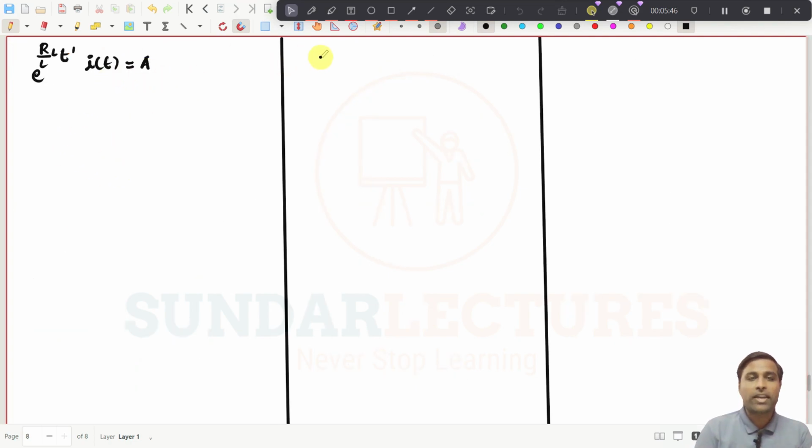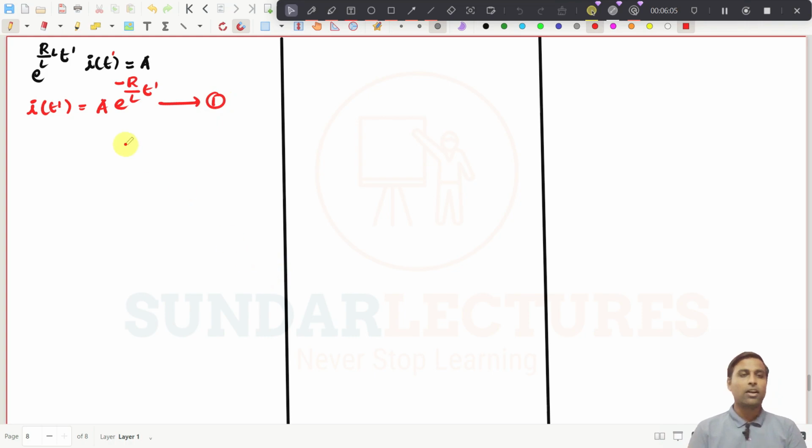Now I can write the expression as i(t'), this is t dash. So i(t') will be equal to A divided by this term, and if I bring it to the numerator, it will be e power minus R by L into t'. Now let me take this expression as number 1. So now we have found the i(t) expression, right? Then if I want to find the value of A, I need to substitute the initial condition, right?